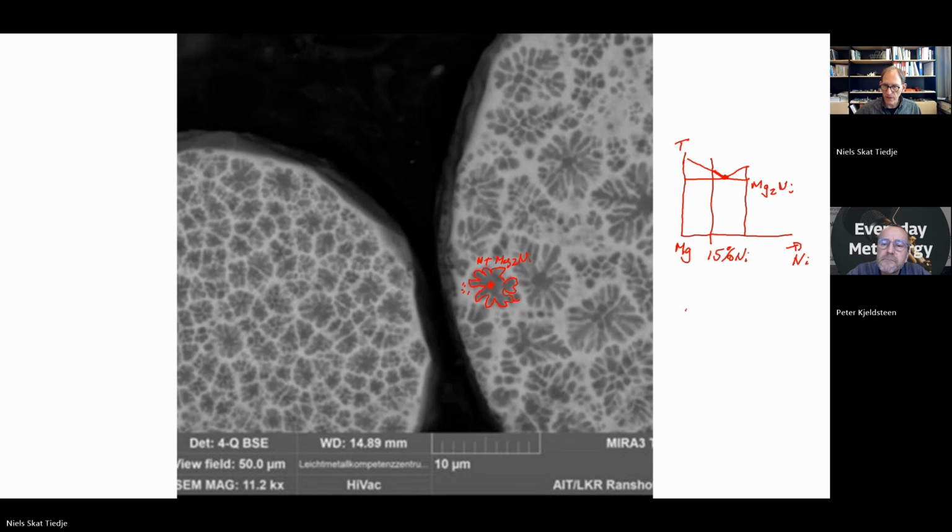But aluminium silicon has something similar. But let's just imagine if we have here magnesium. Then when we look at the phase diagram, from that magnesium, we will have nickel atoms pushed into the liquid. And that means next to it, we will have Mg2Ni. And then we will have more magnesium. And that means that the nickel basically travels from one tip to the next while these materials grow, and it is very simple to exchange nickel atoms, to move nickel atoms from one to the other, and therefore those phases will grow at the same time next to each other.